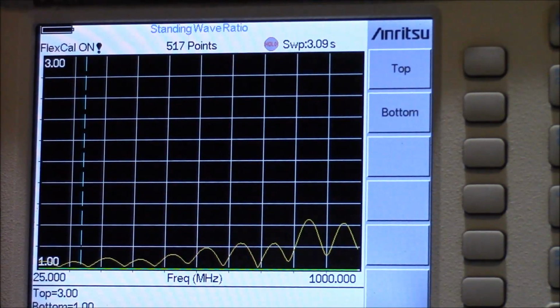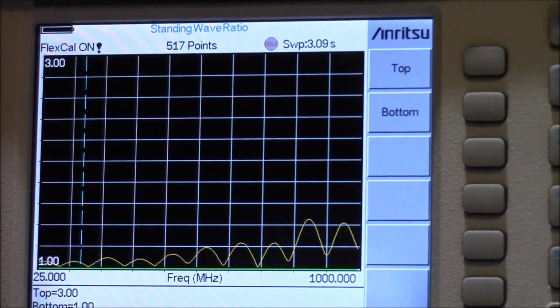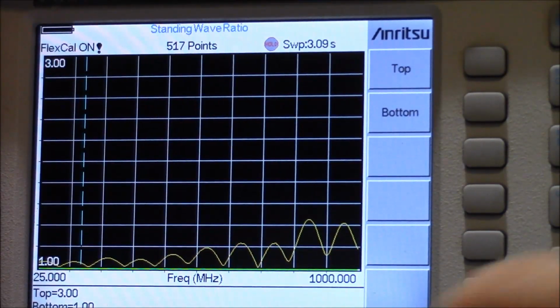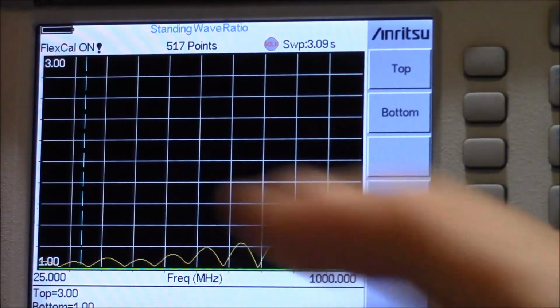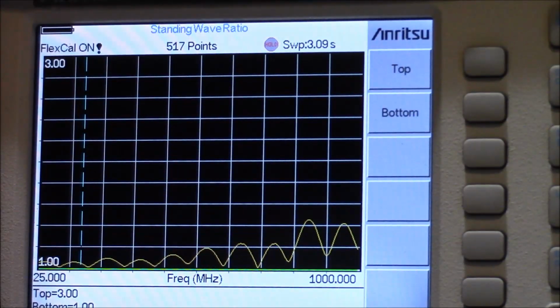So what we can see from our test equipment is that these matched impedances are allowing our test equipment to deliver full output power to our 50 ohm load with a minimum of reflected power.